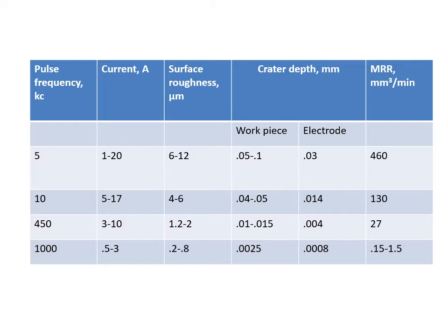It also gives a material removal rate of around 130, which is lesser than desired. So increasing the current decreases the surface roughness, and also the MRR. So optimum selection of the current is a very important aspect here.